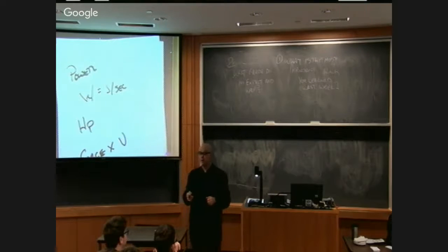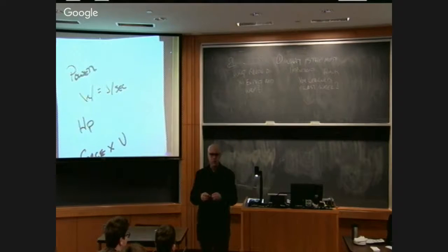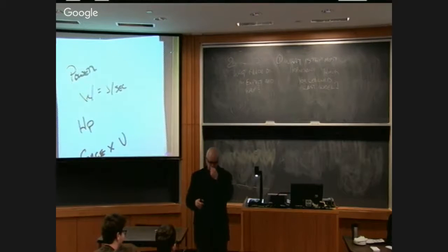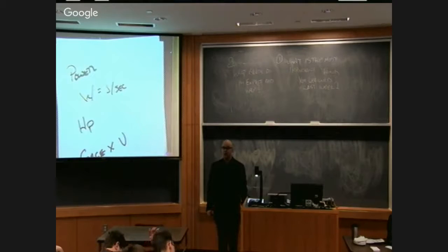Current times voltage, right? Amps times volts, right? So we can measure power, and so how do we measure things like amps and volts? With an amp meter and a voltmeter. Those electrical engineers are not very, what's the word, creative in their naming of their tools. Amp meter, voltmeter. You could use a multimeter that measures both of them, right? So we can measure power pretty easily by measuring the current and the voltage going into our machine tool. And then we can know how much power it took to cut something.